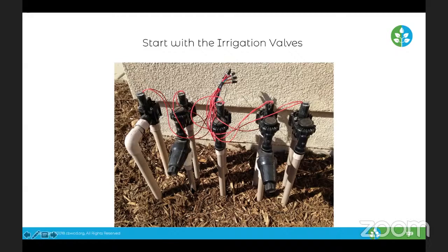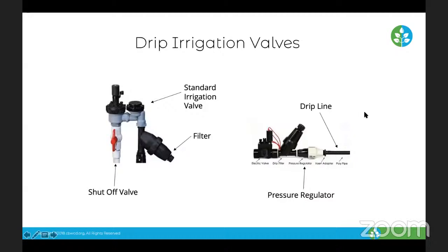That's because our drip tubing is glueless. They're just an insert fitting, so we don't want things to blow apart. And also the benefit of our drip irrigation system is that it's dripping of the water. So a very low, slow volume of water that we run for a longer period of time to give adequate watering, but it's those very small ports, which we call emitters, that allow the water to drip very slowly, which can get clogged very easily, as you could imagine. So we have a filtering system.